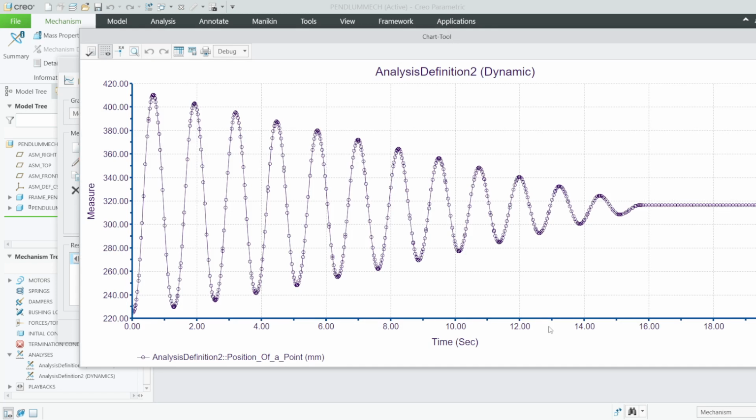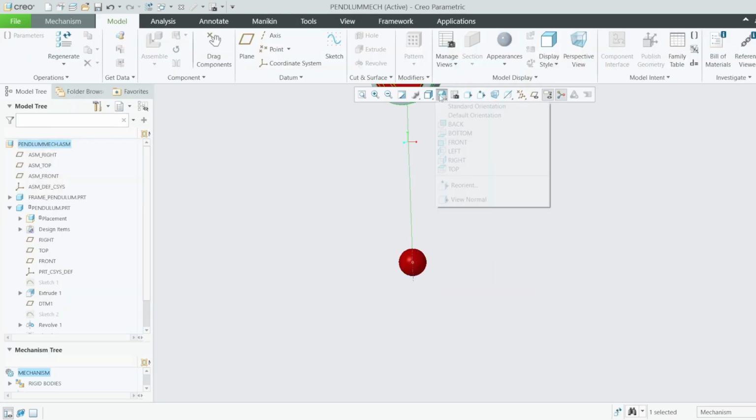And I said I'll show you how to put this point at the center. Let me just activate this part. You can see if you want to put a point at the middle, you can just go to the point here, then select this surface. For references, we have three options: on, offset, or center. Select center. Once you select center, say okay, you're going to get this point exactly at the center. But for now, I don't need it because I already have the point I'm using to take the measurements.